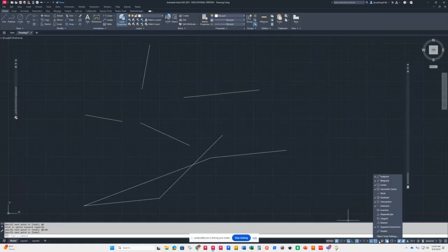Anyway, quadrants, intersection, extension, that's another one that wasn't on the PowerPoint. And then apparent intersections. Those are the ones that I keep on. I'll leave that up for right now. But that's how you can set the object snaps. Later on, we'll talk about the annotation stuff, because that's when we're doing dimension and text. We're going to talk about text, but we're not going to worry about the annotator stuff right now. Okay, so that's all we're going to do for right now.